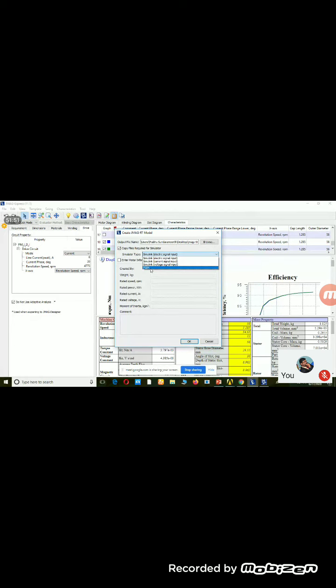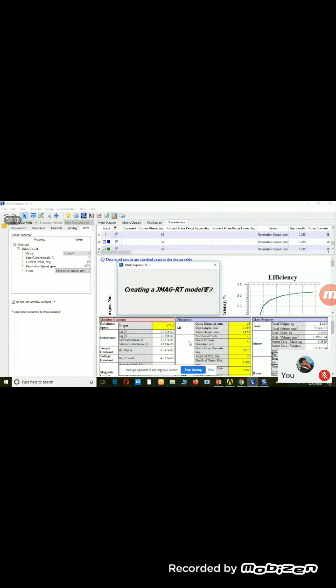So this option is one of the wonders, right? This is another beauty of this package. We can couple the exact model to MATLAB without using an external compiler. Without using an external compiler, we can couple this motor with the MATLAB packages, or PSIM. If you want, we can enable that option, and then give OK. I just give OK here.